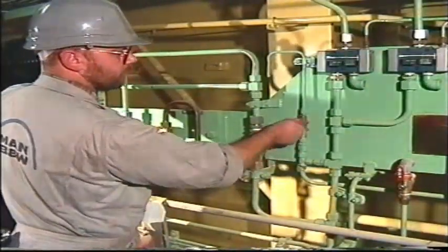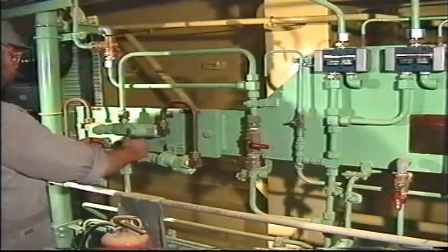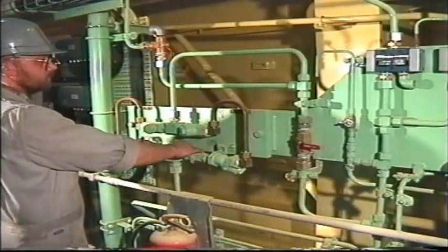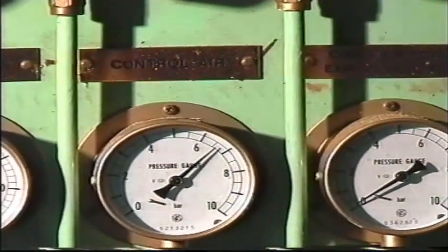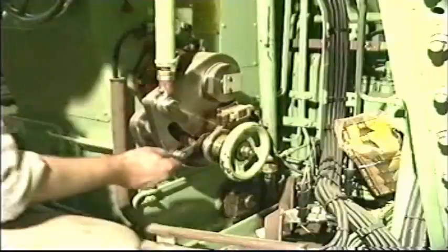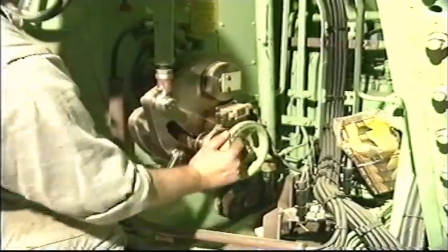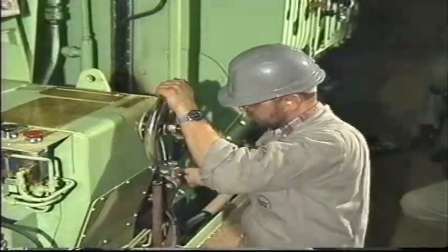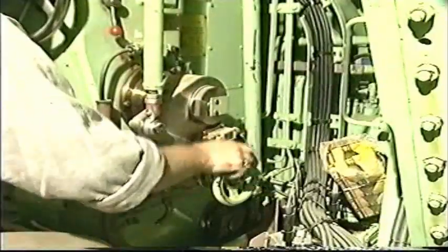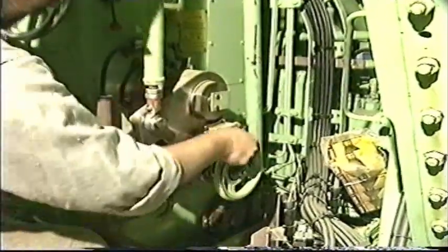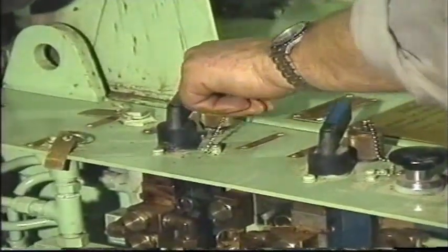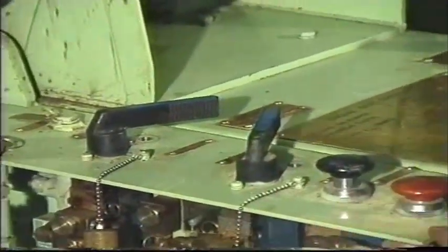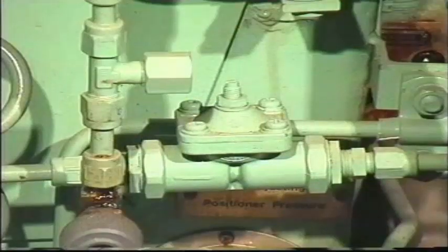Supply 7-bar control air pressure to the pneumatic components on the engine side console. Switch control from the engine room to the engine side console. Turn the regulating hand wheel until the tapered slots of the two levers are aligned. The throttle non-return valve must be fully open before adjusting the VIT system.